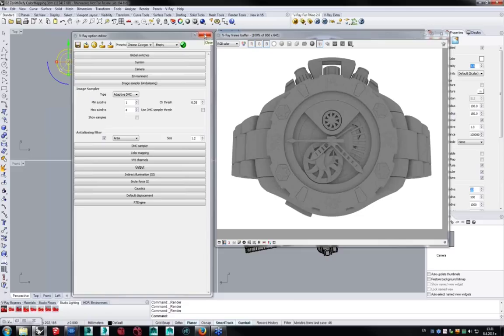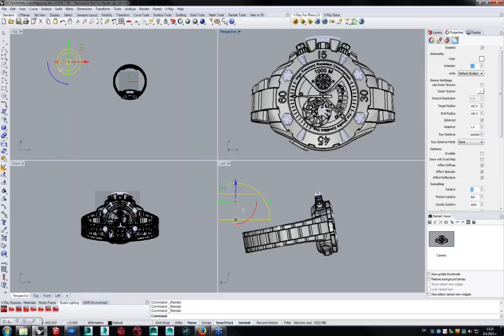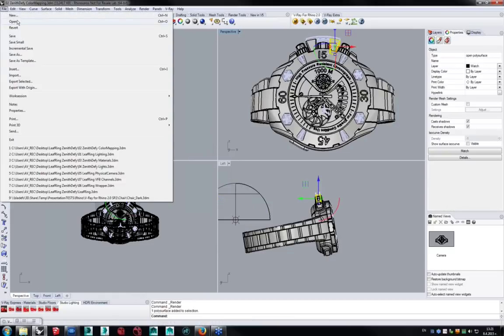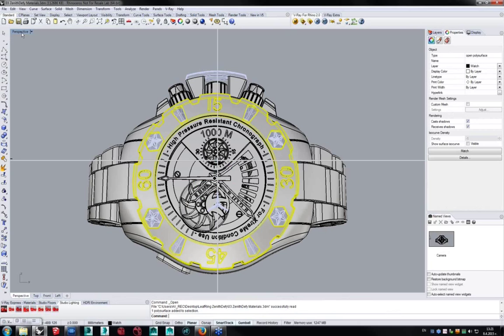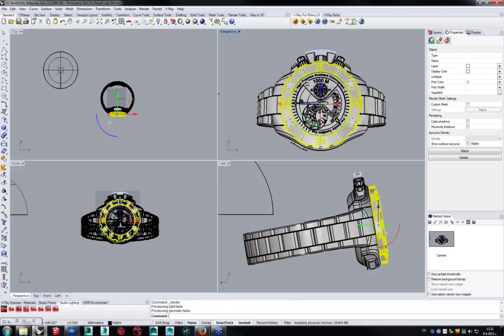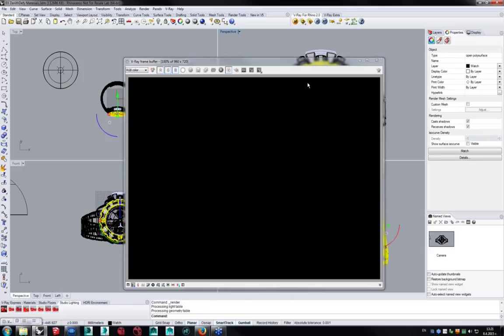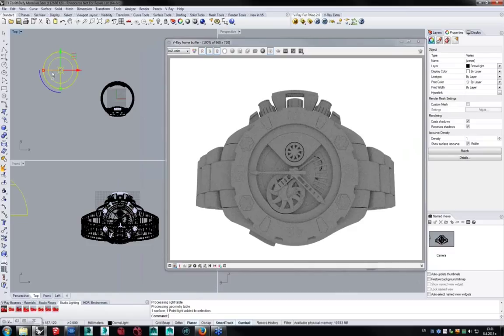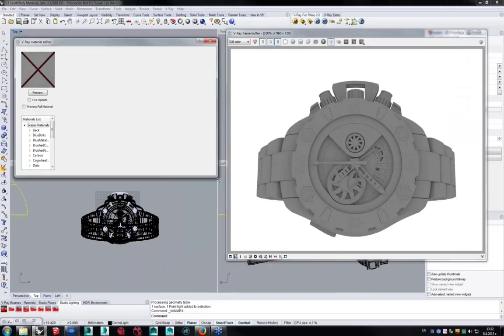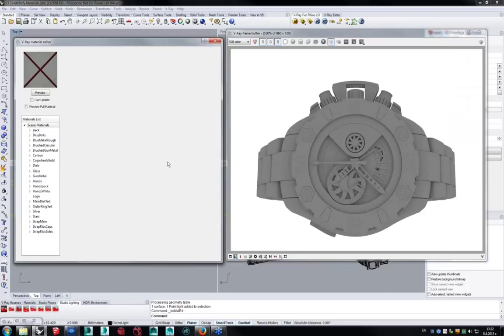Okay, so the next thing that comes after we have determined what type of color mapping I want is the actual materials, because once we are done we can use a controlled environment setup. So here again is the watch, and the DomeLight is here, and I'll just hit the RT now because I want to easily shade my entire watch. There we go. And I'm just going to use the DomeLight because I want to have very uniform light conditions. I don't want to have some harsh highlights or shadows before I at least set up the basics of my materials. So let's open. Currently I have created all the materials, but I have reset them to their defaults.